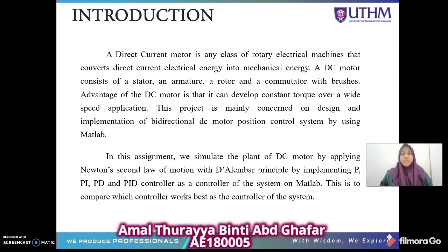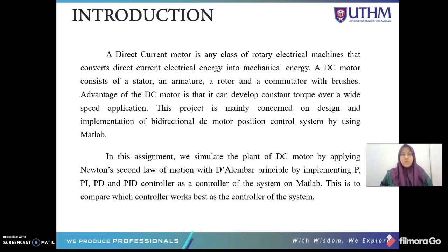This project is mainly concerned with the design and implementation of a bidirectional DC motor position control system using MATLAB. In this assignment, we simulate the plant of the DC motor by applying Newton's second law of motion with the D'Alembert principle, implementing P, PI, PD and PID controllers as the controller of the system on MATLAB. This is to compare which controller works best for the system.